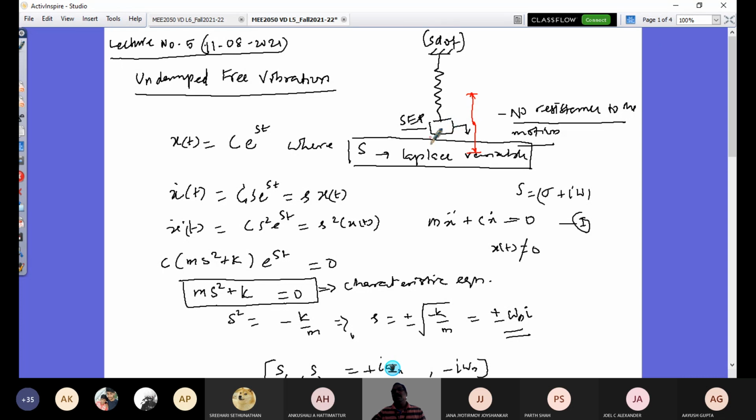The entire kinetic energy is converted into vibrational strain energy, and that strain energy is maximum at its extreme position. Because of that, there will be a reverse motion at the point of reversal. Then the available strain energy, or potential energy, is converted again into kinetic energy, the same amount of kinetic energy with which it started. That kinetic energy pushes the mass up, and then it becomes completely potential energy, and so on.